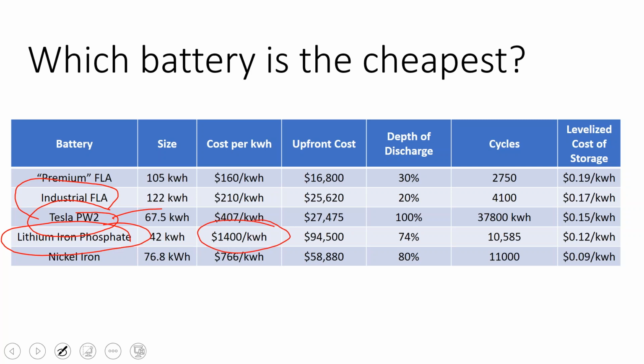And when you're doing commercial demand management, you're not really worried about running out of power because you still have the grid there if you need it. So the total capacity of the battery bank is really less of an issue than if you were doing an off-grid home. And so where the more expensive lithium iron phosphate batteries come into play is not in residential or commercial building design, but in smaller applications like a weather monitoring station or a National Park Service bathroom in the middle of the woods, where you only need a tiny amount of power to power your instrumentation and monitoring and LED light bulbs, but you never want to step foot on that site again for the next 30 years.